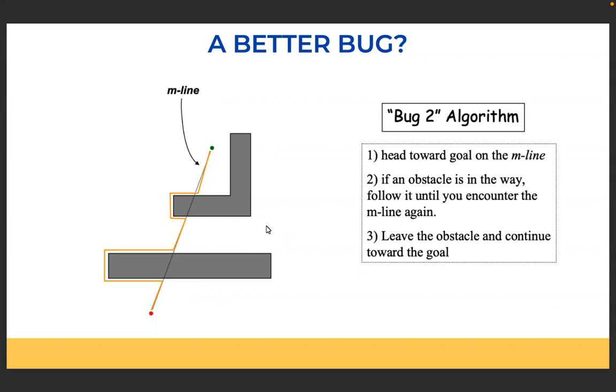Even here, there is some memory storage. You have the start location and the goal location. You can form a straight line, okay? And then you store in memory each of the points on that straight line. You can construct an equation of a straight line if you know the two points. You basically discretize all these points. You know all the points that lie on this line.